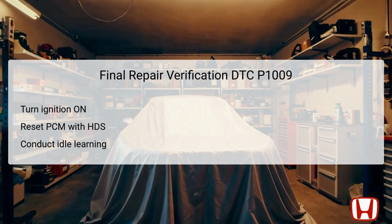The next step involves resetting the powertrain control module, PCM, using the HDS, which clears any stored fault codes and refreshes the system. After that, conduct an idle learn procedure, which allows the PCM to recalibrate and adapt to newly installed components after repairs. This step ensures that the engine management system can adjust itself appropriately.